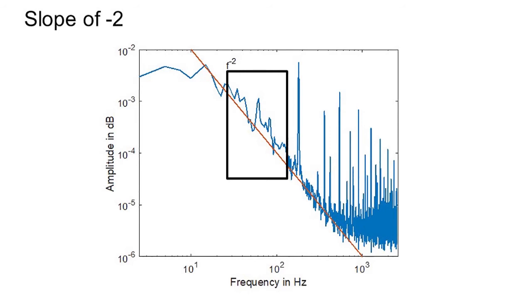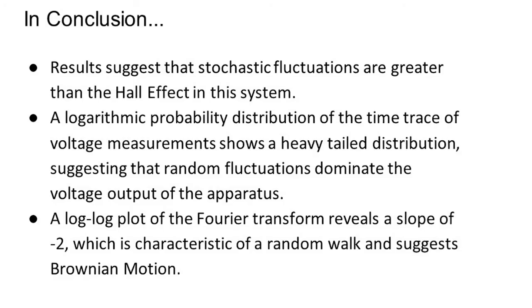The way that we have been theorizing about this is that as you have different polystyrene particles with charges of all sorts coming in and interacting with that copper tape electrode, you've got a positive charge depositing its charge onto the electrode, resulting in an upward spike. And then a negative charge depositing its charge, resulting in a downward spike, which can then be modeled by using this random walk.